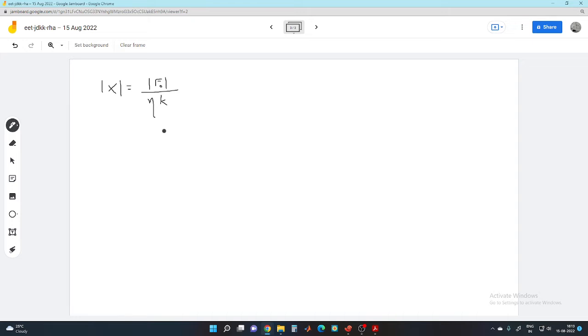Now we have a linear bar, right? So for a linear bar, like this bar, if this end is fixed and this end is applied with a force, here we'll say F1, and the extension at this point is x. As per Hooke's law, the linear Hooke's law, we are assuming that the spring material is purely linear elastic. So it will become sigma equal to E epsilon.